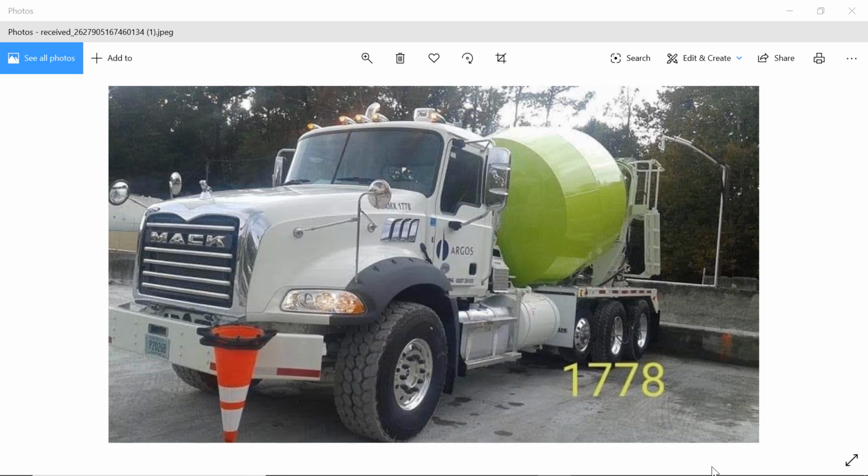Example 6. The example design mix calls for 1,366 pounds of fine aggregate and 267 pounds, 32.0 gallons of water per cubic yard. The aggregate has an absorption of 1.40% and the total moisture content is determined to be 2.81%. Calculate the adjustments to batch quantities per cubic yard. Figure the water adjustment in pounds and gallons.